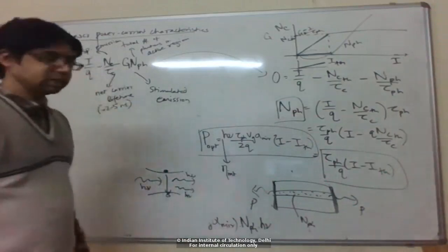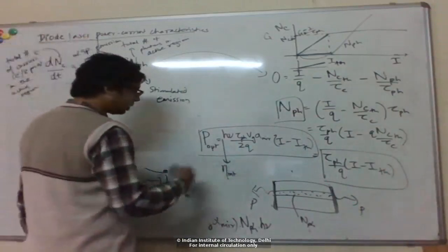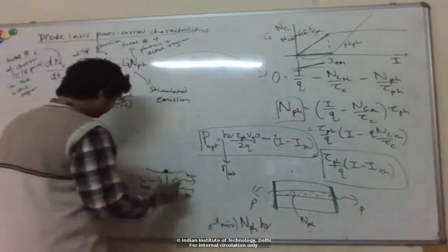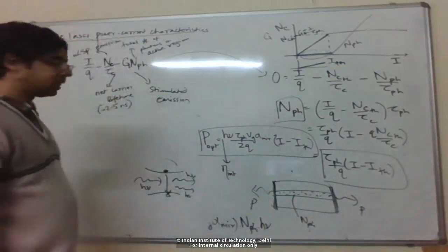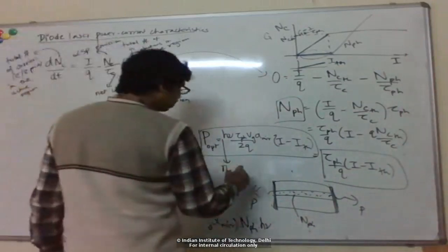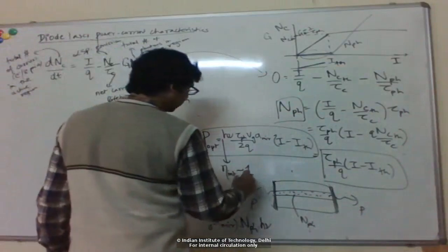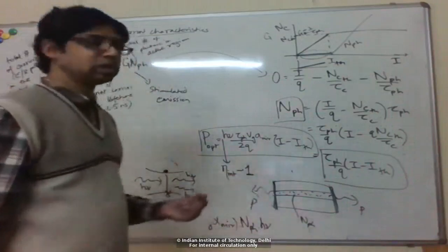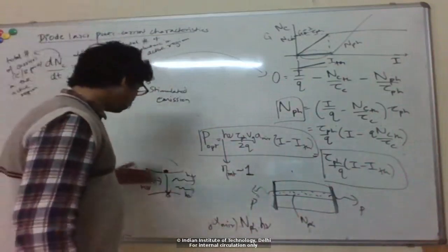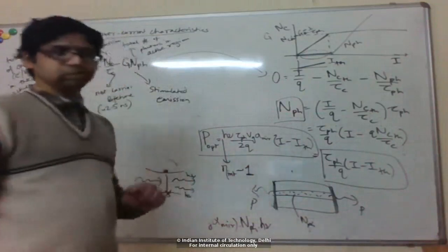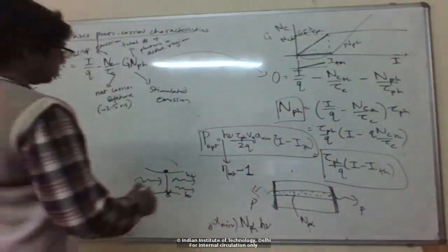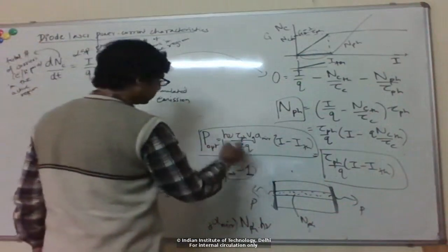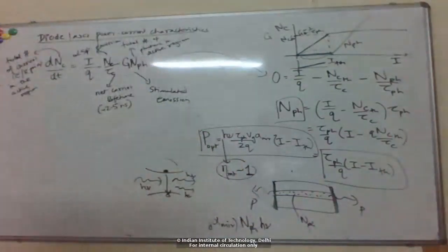So we can define an equivalent internal quantum efficiency for that, saying that the stimulated emission is not perfect 100%, but maybe slightly less. Practically, this is still very close to 1. Once you go into stimulated emission, with 95% or more efficiency, you generate a new photon. So sometimes you might see this additional factor here, but mostly we just assume that to be close to 1.